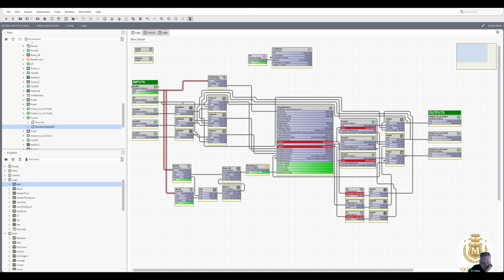So we're doing a B, now a C, and when it all stops, it'll be back to A. So that's your reset done. And they're going to go into fault because we haven't got our DP on. So that's going to go into fault. Then B is going to go into fault after 10 seconds. And then C is going to go into fault after 10 seconds.